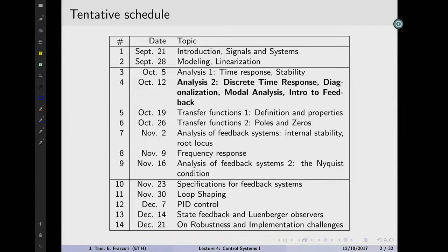But we noticed that these systems really are not representative of what's actually going on, right? Because the things out there tend to be nonlinear. But we noticed at the same time in last class that if we proceed smartly about it, we can always use linear time invariant systems as approximations, local approximations of nonlinear systems. So if we linearize a nonlinear system around some special points, which we called equilibrium points, we get a good approximation of the dynamics of the nonlinear system.